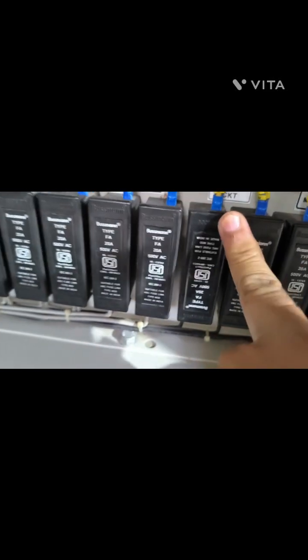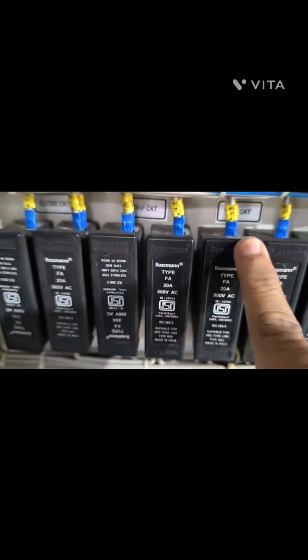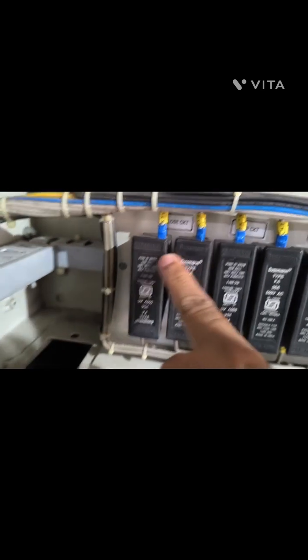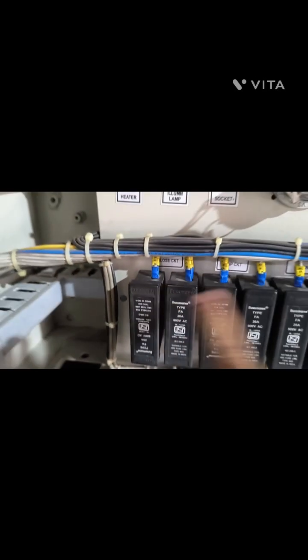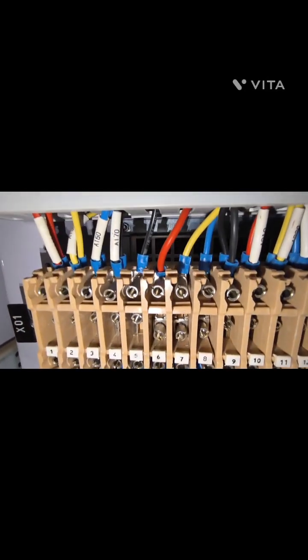Next is your auxiliary supply, that is for relay, everything is PT supply requirement, that is E, PT supply. L means annunciation indication circuit, L. This is also indication circuit, annunciation indication circuit starts with L. Whereas this is the trip circuit and close circuit. These are all CT cables, and the Ferrule you can see here starting with A.